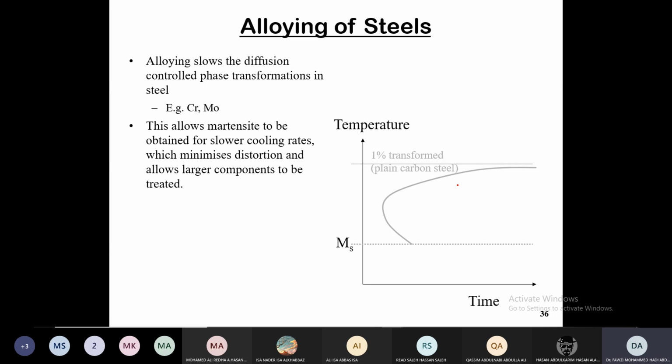The quenching of martensite, we said, sometimes, if large pieces are considered, causes cracking of the material. But even if it does not cause cracking, it will cause internal stresses in the material. One solution to resolve the problem of cracking or internal or residual stresses in the material was tempering, because it anneals out any internal stresses in the material, if there are any.